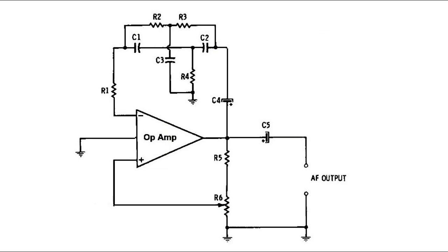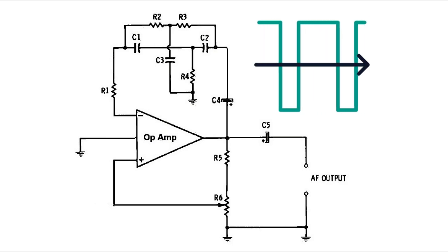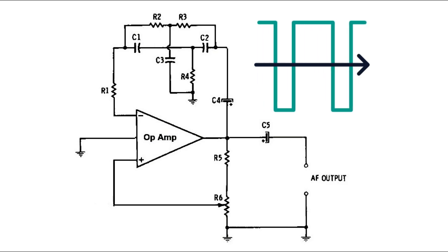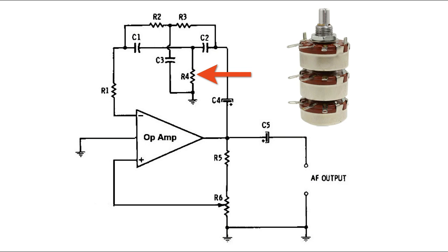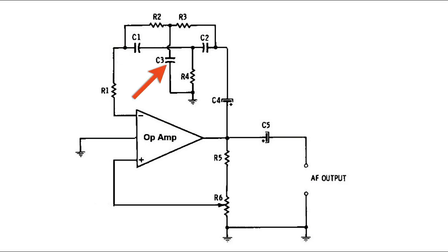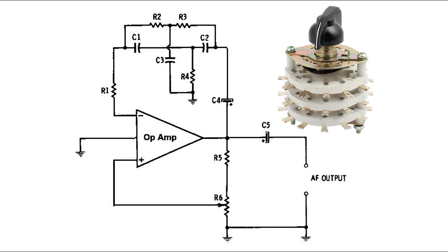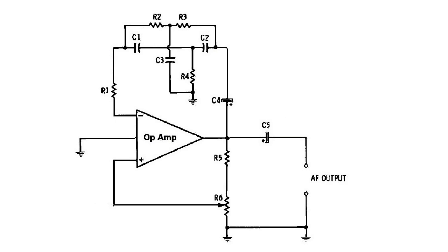The op-amp oscillator circuit could be made to work like a continuously tunable oscillator, e.g. from 20 Hz to 20 kHz, simply by replacing the resistors R2, R3, R4 with a 3-gang potentiometer, and selecting capacitors C1, C2, and C3 in trios to adjust the bands. Output control could be accomplished through a potentiometer which may be configured either at the output or introduced between stages of the IC.